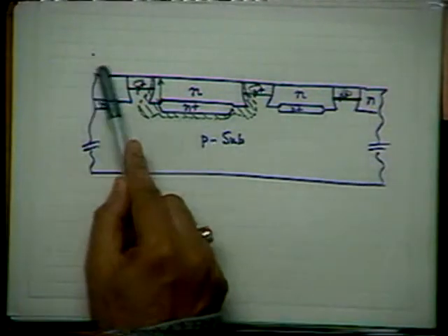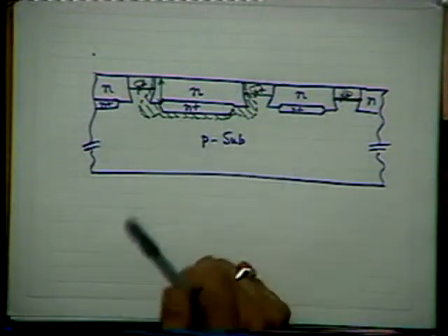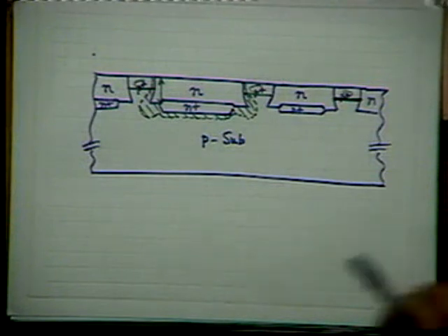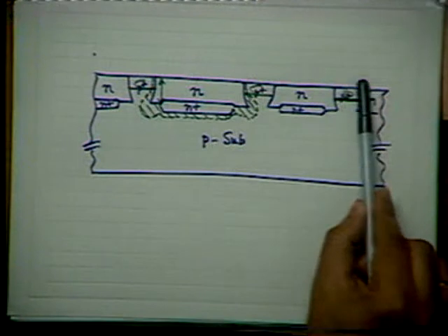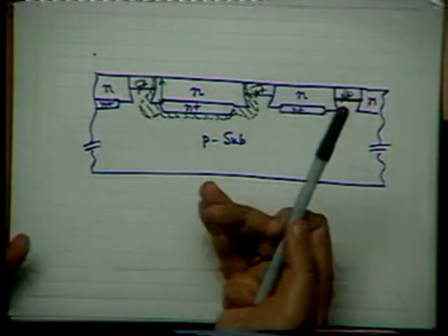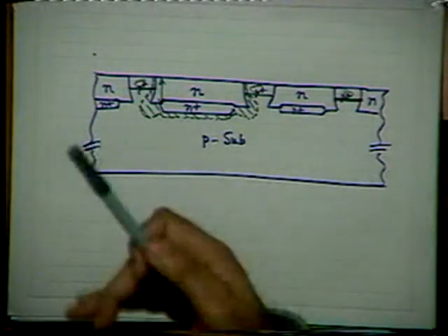The island regions are all covered by a nitride film, silicon nitride film. The technique is such that all the island regions are covered by silicon nitride films, whereas in these regions silicon is a little bit etched. About 50% of the epi layer silicon has been removed. I grow silicon dioxide by wet oxidation technique.